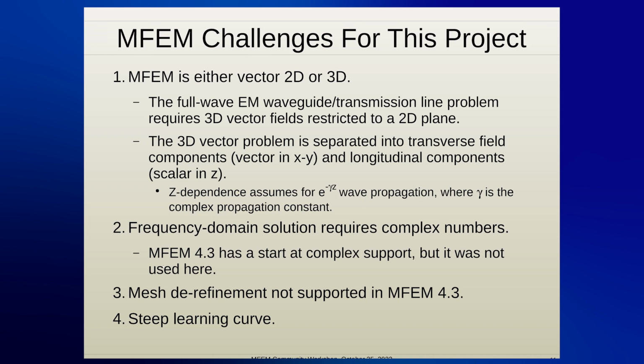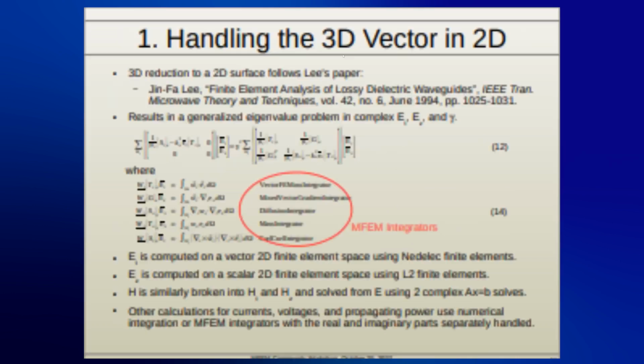Third issue I had, mesh derefinement is not supported. At least I couldn't figure out how to get it to work. I'd get an error message that it wasn't supported, and I never found a workaround. So I'm going without derefinement for now. And then I found, at least for me, a relatively steep learning curve. So I'll go through 3 of these to provide a little more detail.